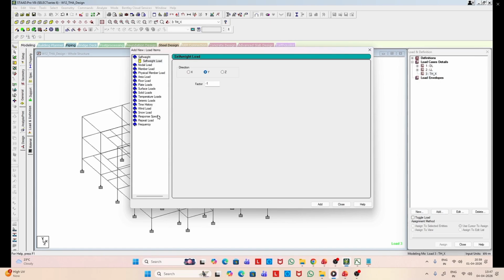Now here, recall the time history is in G. So here you can select the time load or ground motion. For our case, it is ground motion. So let us select ground motion here. Direction is along x. Arrival time is 0. And here you see the defined type is acceleration, and the force amplitude factor we have to apply because the original accelerogram is in G, so we have to multiply that with 9.81. So here we have to set the force amplitude factor as 9.81.